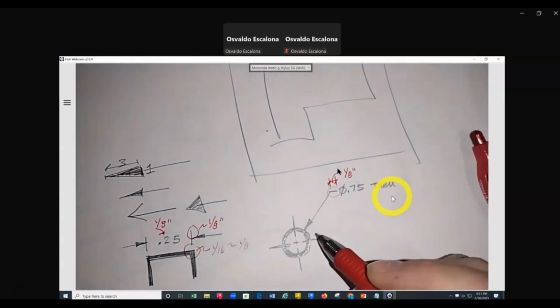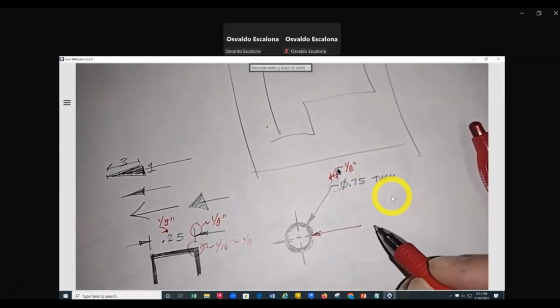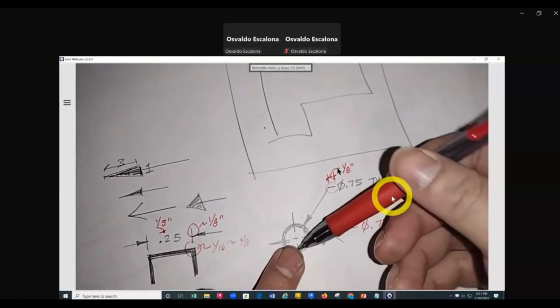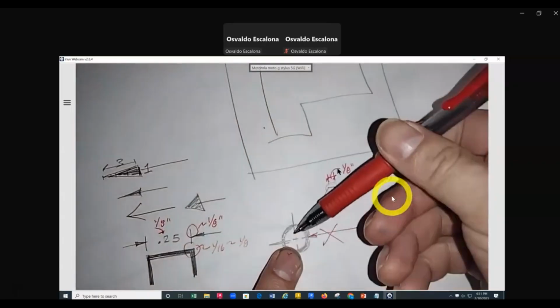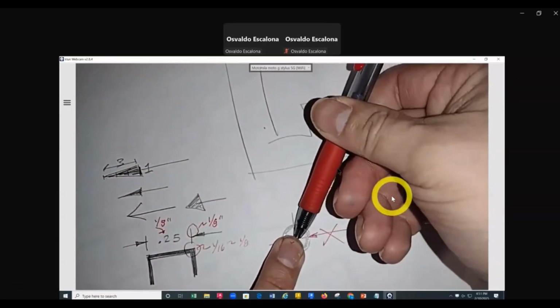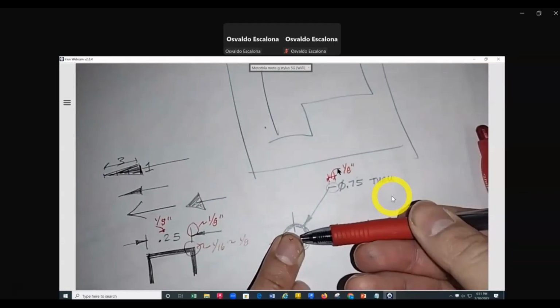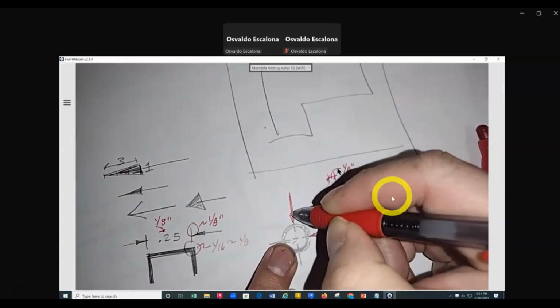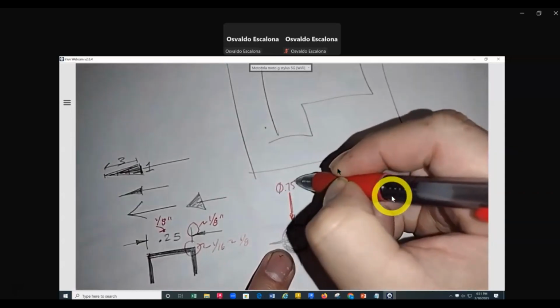Don't do this. Don't do this. This angle is between 30 degrees to 60 degrees, nothing more. You don't put the arrows like this. There should always be a little shoulder. Don't say, oh, I'm going to put an arrow like this and call this like that. No.